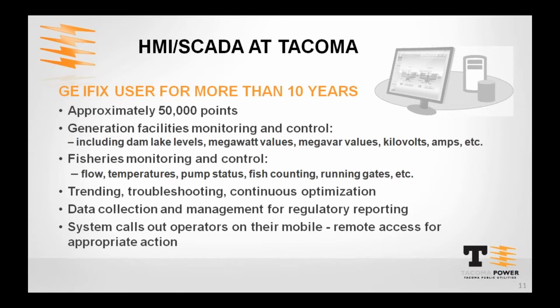On the fish hatchery side of things, we've added some additional capabilities for call-out. So if there's an alarm, it actually interfaces with the HMI SCADA system that results in a call-out if there's a critical alarm that they need to be called in for and to check out. The HMI system is used for trending and troubleshooting various issues that occur, as well as looking at historical data. When it comes time for regulatory reporting, we rely on having that data available.